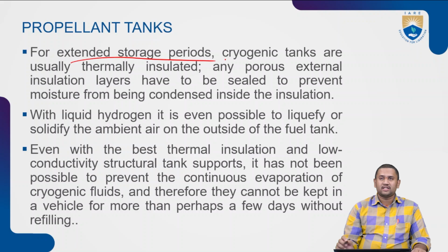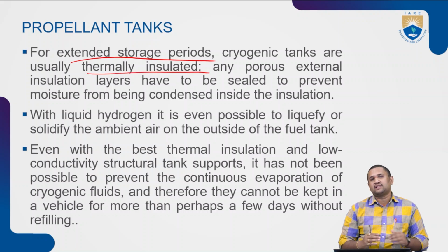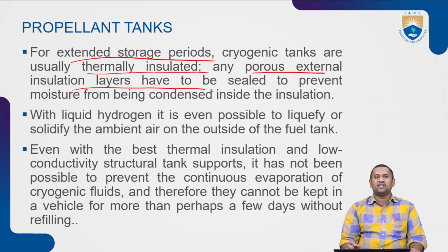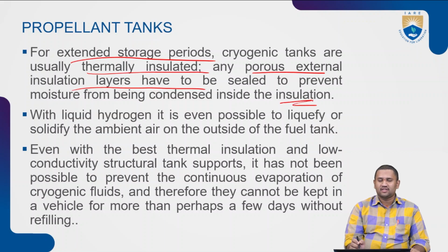For extended storage periods, cryogenic tanks are usually thermally insulated, meaning no thermal interaction from the atmosphere or the surroundings to the tank. Any porous external insulation layers have to be sealed to prevent moisture from condensing inside the insulation layer.